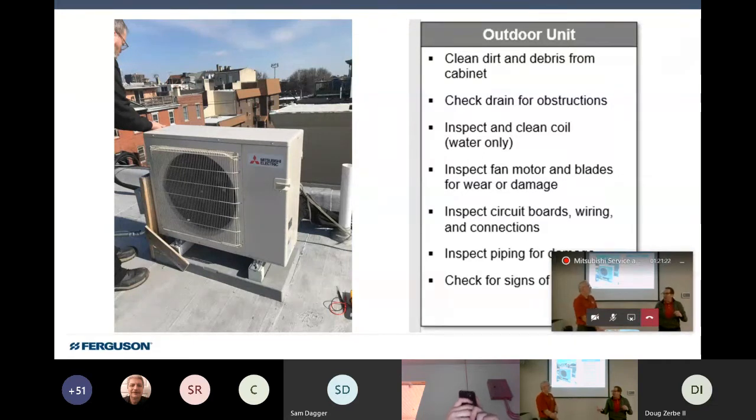We wound up pinching a finger, I'm feeling for kinks. And you all have been there. You feel through the Rubatex, and it's like, is that a kink or not? So you take your thumbnail and you kind of pinch, and as soon as I pinched that, I got sprayed with water. The water rolled out of that Armaflex onto the ground. And I would say that it was at least a 16-ounce cup of coffee.